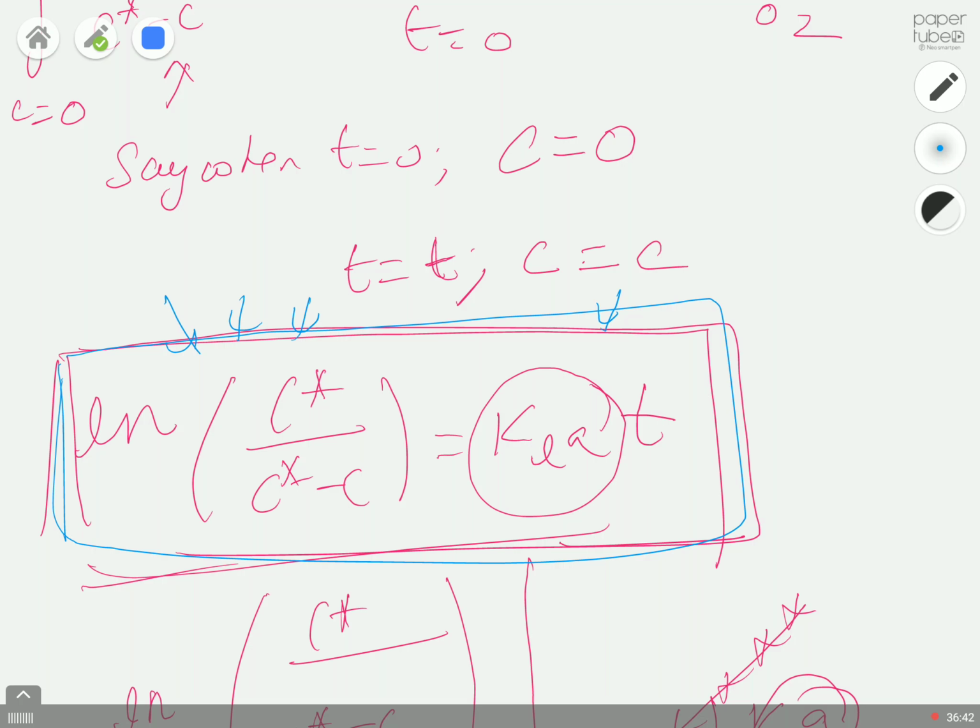Like you have a reactor, or a fermenter, and you have some aerobic bacteria inside, and they need to breathe. For that you need oxygen. Without oxygen they're not going to survive, because all of them are aerobic bacteria. Where are they going to take the oxygen from? The oxygen comes from the liquid, which means you have to dissolve oxygen in the liquid. For that you have to supply some oxygen gas. Obviously you can supply it as bubbles.